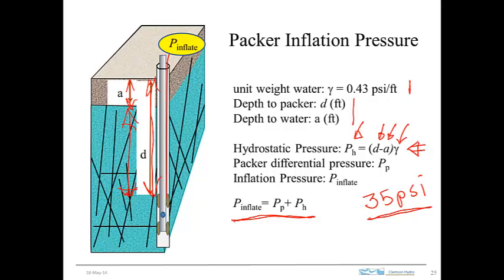We have another packer in the trailer that is typically inflated to about 500 psi, and when you do that, you have a much tighter seal on the borehole, and you can generate much higher pressures within the packed off interval. So when we do a slug test here, because we only have 35 psi of pressure on the packer, we can only have a small fraction of that pressure be applied to the zone between the packers, the straddle interval.